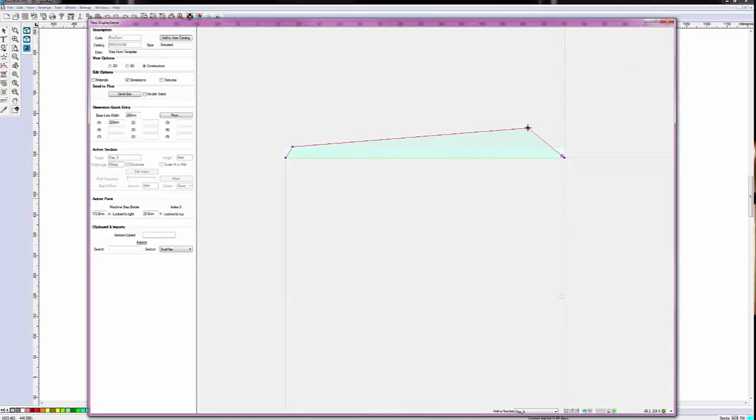I can use the shift key to make the point horizontally or vertically aligned with the previous or next point. You have to try this to see which it will be, and then I can left click to get a value on the same vertical level as this point.